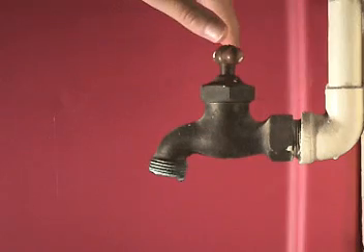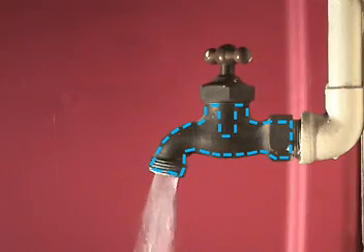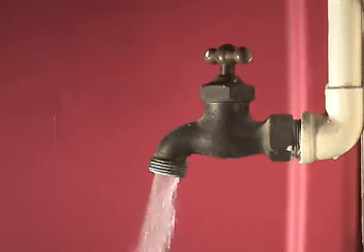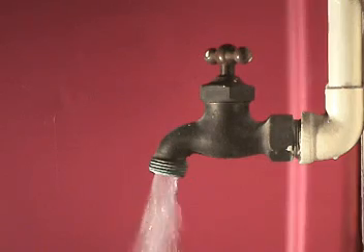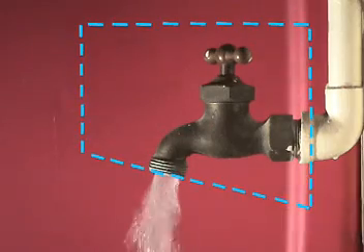This comes with experience, but here's a simple example, a water faucet. We could draw a control volume that exactly surrounds the water flow, but analyzing it requires boundary conditions that are not easy to figure out. A simpler overall approach is to include the entire faucet in the control volume and simply slice the flow perpendicular to the inlet and the outlet.